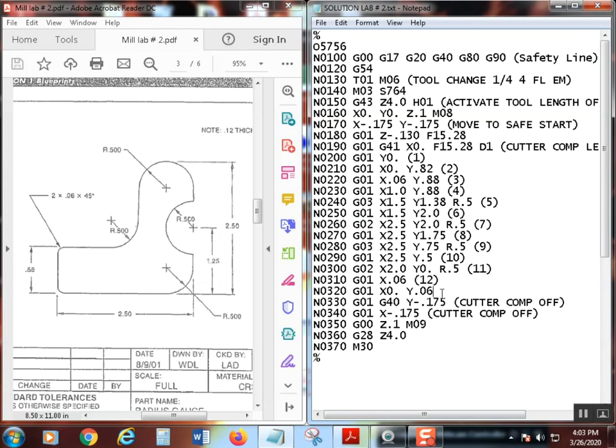All right, next point, 13. At this particular point, since this is a chamfer, remember, 60 on one side and 60 on the other, we're going to G01 to X0, and Y is going to go to 60 thousandths. Because we were at X 60 thousandths, we moved both axes this time. That's why we get our little chamfer, our little angle there.